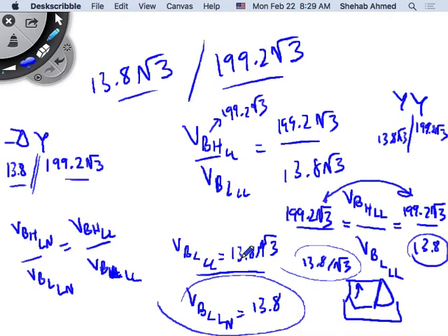As long as you make sure the ratio of the bases is equal to the ratio of the terminal voltages. Then you choose a base on the star side. This is a choice, or I will ask you to take a base, like in the homework problems where sometimes you're told to use 132 kilovolt as the base in zone 2, for example. So this is based on the choice. Then you will find the missing one here.